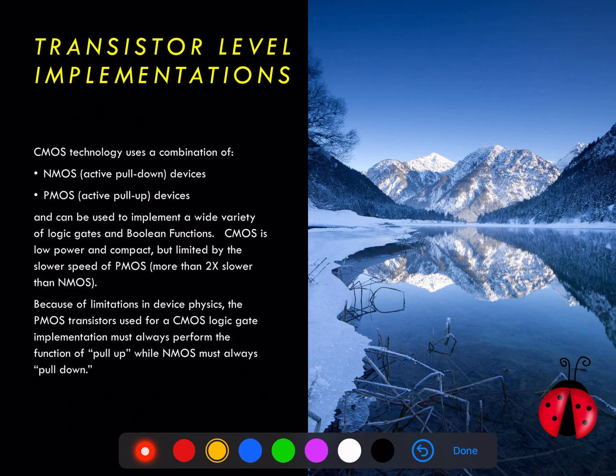So what we've looked at today is CMOS implementations of various types of logic gates. The basic logic gates, inverters and buffers, as well as ANDs, NANDs, ORs, and NORs, as well as XOR, XNOR, and some more complicated Boolean functions. Because of limitations in device physics, the PMOS transistors in a CMOS gate always perform the function of pull up, while NMOS must always pull down or make connections to zero. Well, that's all for CMOS implementations of digital logic gates today.